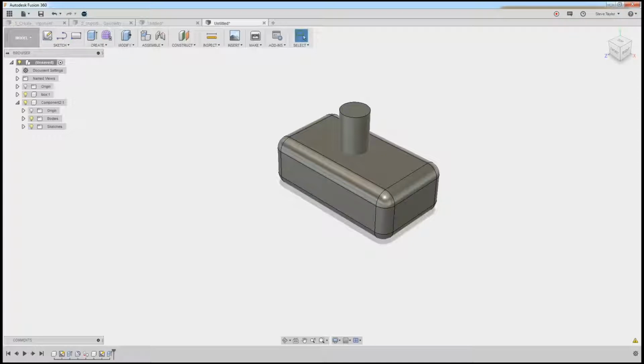So if you're in a hurry and you say we need components to do joints, do drawings and stuff, if I've been in a hurry and I've just done a concept design just using bodies, I can go back and I can create component from the features. I can create it from the bodies. Can always move and add them and create what I need, the bodies and the features and the sketches for a particular component, and move it around in the folders to correspond to what I really needed. So you can always go back. It's flexible the way that you do it.